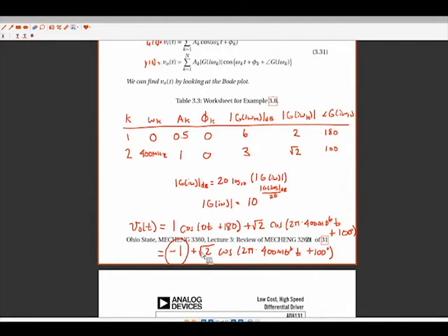And then you get up to a certain frequency, and then this no longer behaves in an ideal fashion. You're above what's called the bandwidth of the system. The system is designed to behave a certain way. Any physical system is going to have a trail off, and the magnitude is going to decrease with increasing frequency as we get to really, really high frequencies. So this op amp is very, very fast. 400 megahertz is extremely fast, but it's still not an ideal system. At that frequency, it starts to trail off. You can directly see that in the Bode plot.